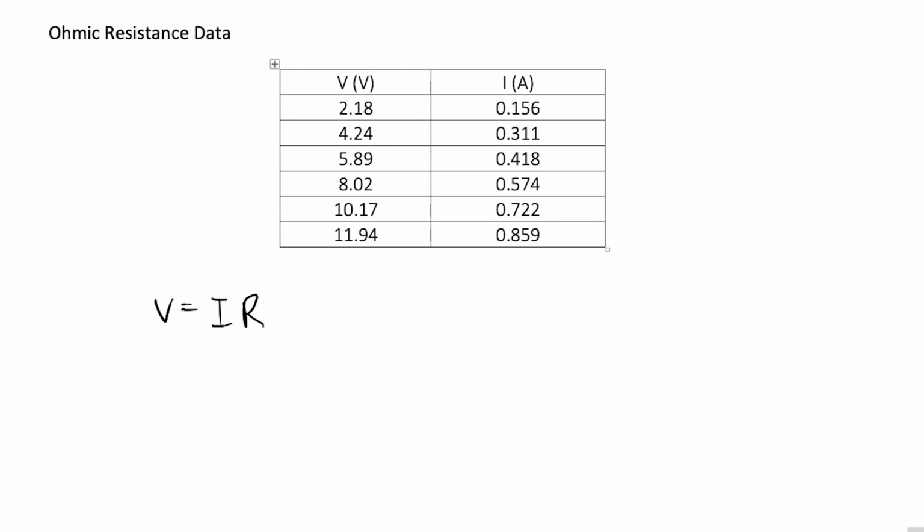Now, usually our least scale deflection times a half is our uncertainty if we don't have another method of establishing uncertainty. So our least scale deflection is 1/100th here. So each of these voltages is going to be plus or minus 5/1000ths, 0.005, because that is half of this last unit, 1/100th. So that's our precision in those.